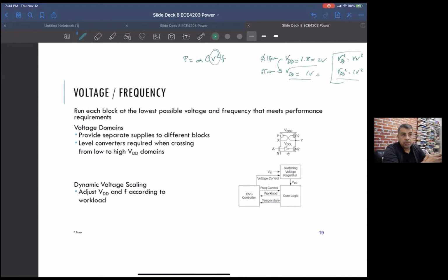They are much more expensive from an NRE standpoint, a non-recurring expenses standpoint. The 65 nanometer process is a lot more expensive to design into than a 0.18 micron process. For a 0.18 micron process, between the mask set and the wafers for an engineering run, you might be looking at $200,000, say $300,000. For a 65 nanometer process, you might be looking at 2 or 3 times that amount. But look at all the stuff it gets you in terms of power consumption.